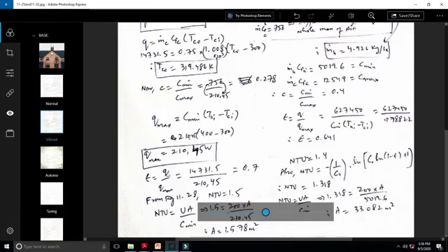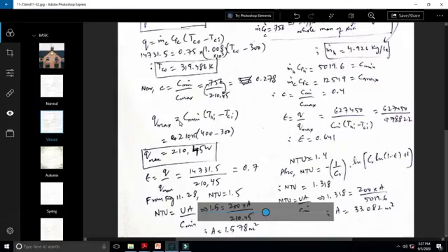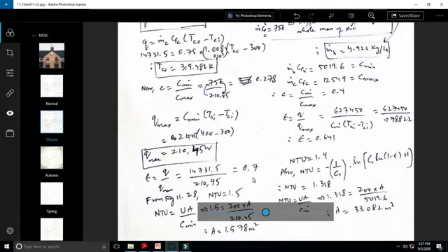So we will get maximum Q as 210.45 multiplied by 100, which is 21045 watts. So Q, which was calculated as 14731 divided by 21045, gives us 0.7. So effectiveness is 0.7.